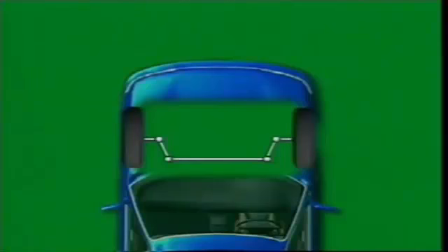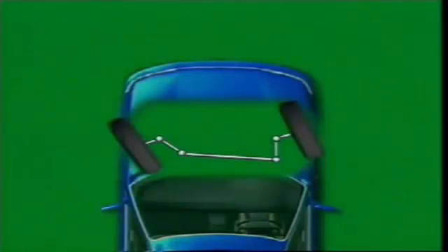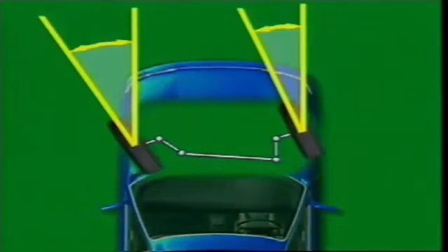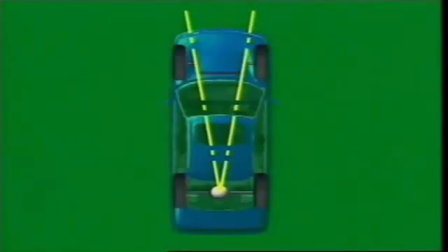With the steering linkage at the rear of the wheels, the distance across the tie rod ends at the steering arm joints is made shorter than the distance across the steering axis swivels. This forces the inner wheel to turn through a larger angle when the steering is turned. The Ackermann angle is the angle the steering arms make with the swivels on the center line of the vehicle at or near the center of the rear axle.